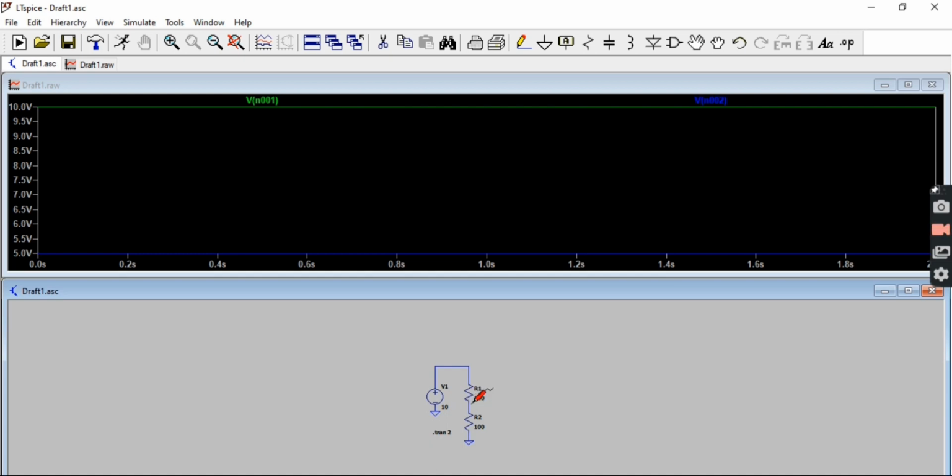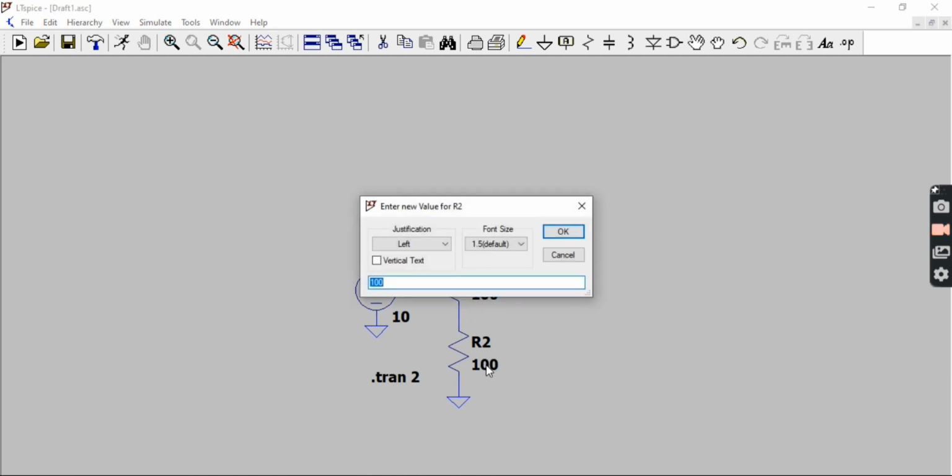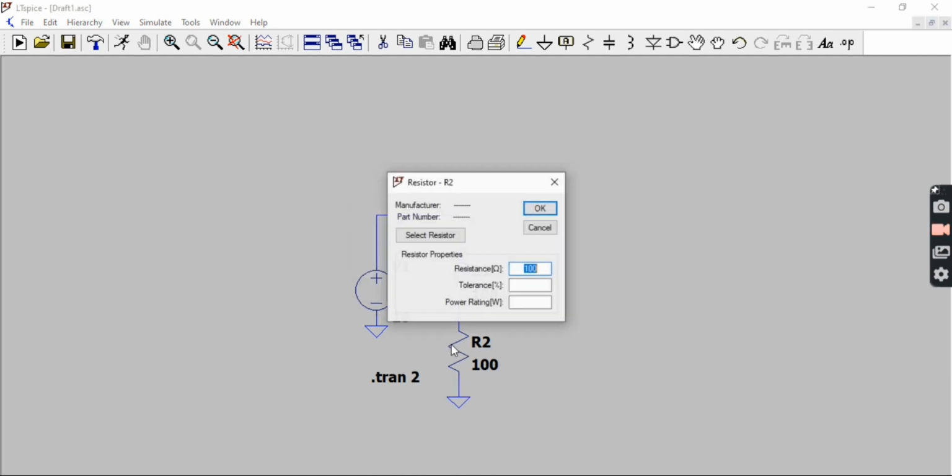So this is how you can draw a basic circuit. And now how to get rid of this? You can directly close that, and you can maximize it. Now you can change things here by putting any capacitor or anything. But this is DC, so nothing will happen with the capacitor. You can add more resistance, and you can change the resistance value also, by right clicking again on the component and changing the value. Let's say I have changed it to 200 and say OK.